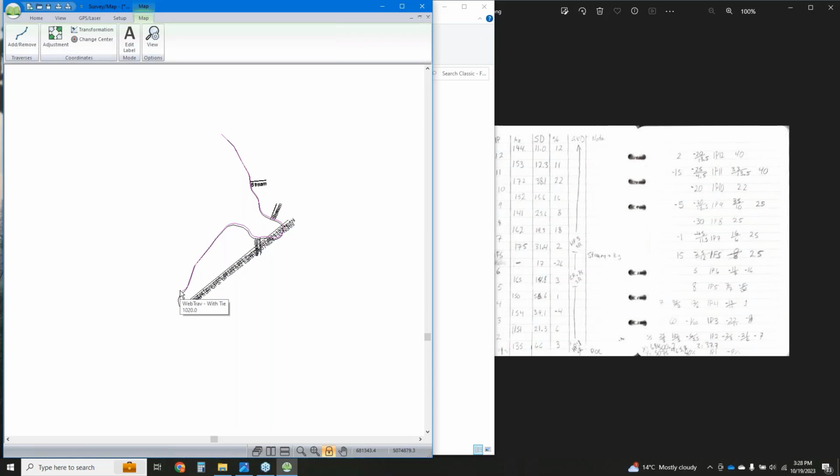It fits those hard ties. So in this case, I have a hard tie at the start, and a hard tie at the end. Everything else gets wiggled around, but you can add those hard ties throughout if you have good measurements on spots where you know the actual survey should be. All right, that's the main talking points for the data entry side of it.